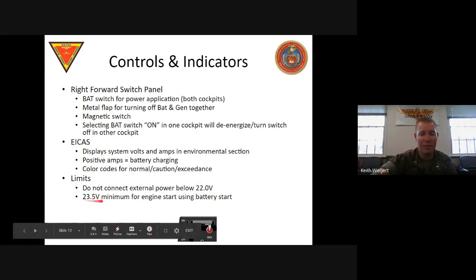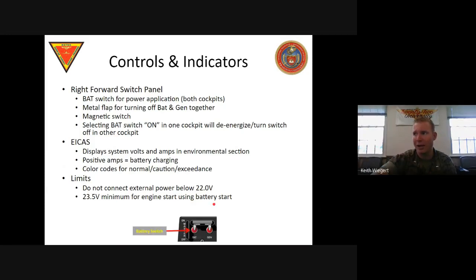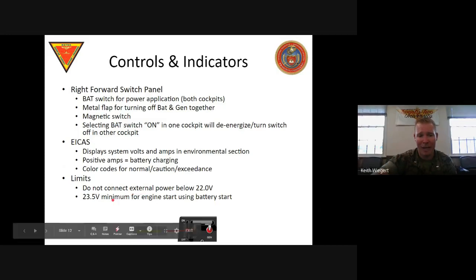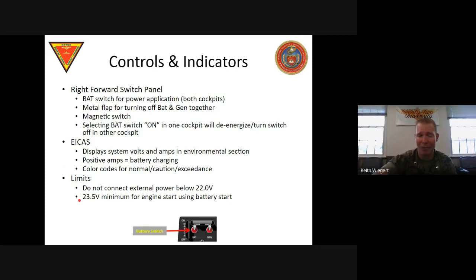And then 23.5 volts is the minimum for an engine start using the battery, right? So if you don't have an external start cart, or whatever, you cannot start it if you've got less than 23.5 volts on the battery. Remember, it's only a 24 volt battery. So it's like half a volt there.